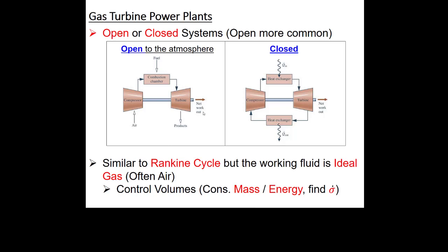So it's like a heat engine, which means it's like a Rankine cycle and it's like an internal combustion engine. But here, always when we do the analysis, when we think of each individual process, it's an open system, right? So we're going to use the same equations that we used when we were talking about Rankine cycles. But like an internal combustion engine, the working fluid, although it's really some complicated and changing mixture of air and fuel, we're going to say that the working fluid is just air. So it's mostly like Rankine cycles, until we get to the...